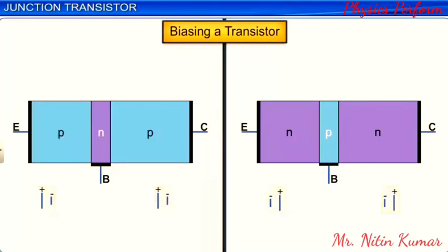But the transistor has only 3 terminals. Hence, one of the terminals is made a common terminal to bias the two p-n junctions. The emitter, or the base, or the collector can act as the common terminal, and based on this information, the configuration of the transistor is named accordingly.